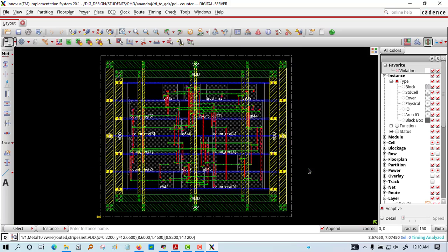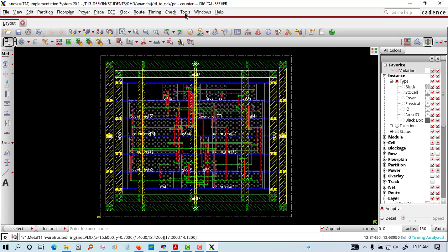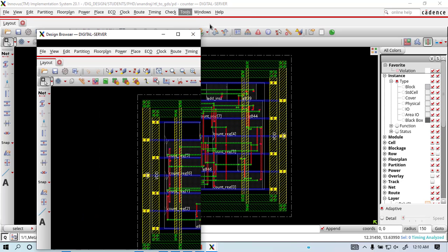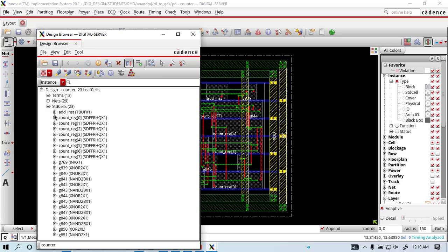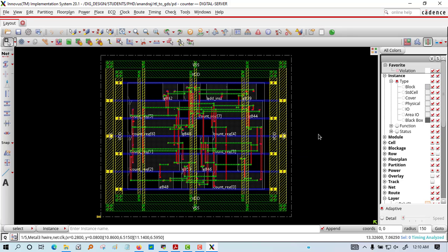These all are the same. Okay, so add instance G839. These all are cells, because if you want to see what cells are there, you can also see from here, right? So see, G839, G840, these all are standard cells, and a flip flop is also there for count 0. All these are automatically placed using the command which we have given in the terminal, right? So they are automatically connected based on optimization, like minimal distance and minimal power, and everything has been optimized and placed.